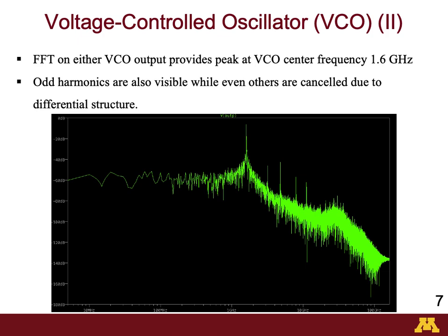Therefore, we might have to go back and forth a couple of times to obtain the desired resonance frequency that we're looking for. If we do not know the varactor capacitance for a particular two-terminal voltage in the first place, which we do not, we have to go back and forth to fix that. Maybe once or twice iterations should be fine.